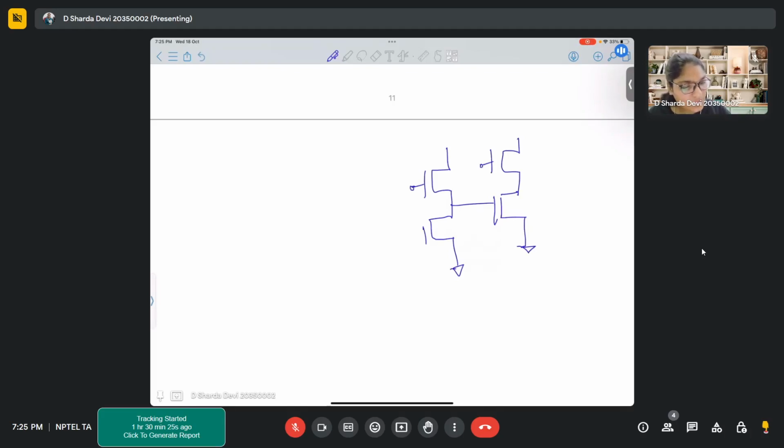There are certain voltages, like let's say here VA, here you have VB, this is VDD. This is where you are applying your test voltage, correct? And you have your IX. Now the point is, here there is a capacitor, which is the Miller capacitor, internal capacitor. Now this IX is flowing, so how will this IX flow? It will get divided, ma'am.